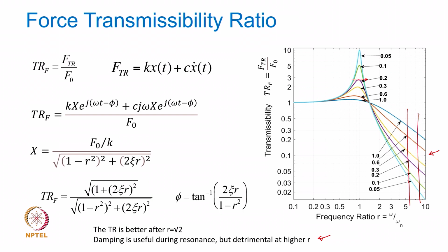to add any extra damping to the system, because the amount of material damping that is there in structures like steel or any mechanical structural material would be good enough. Yes, it will be good enough definitely when you are operating. The structural damping ratio for steel, as we know, is roughly of the order of 0.005 or 0.01 at the most. So, the upper limit could be of this order, and with that you will be really comfortable here.